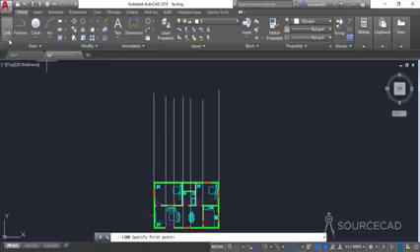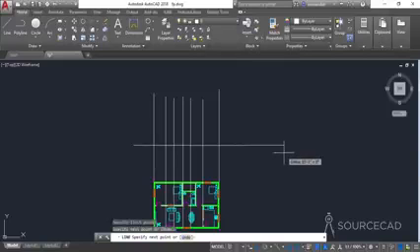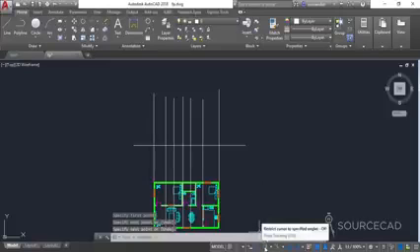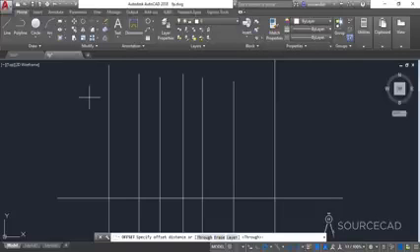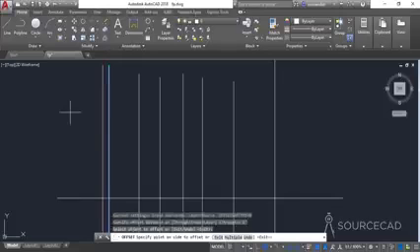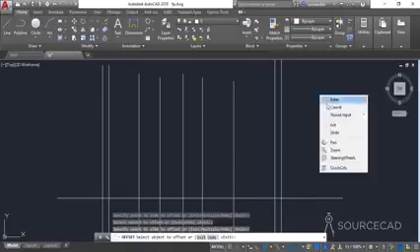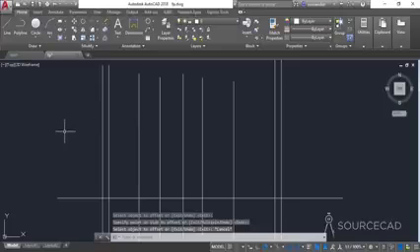Let's make a horizontal line. So I'll go to line tool and I'll roughly choose this point and I'll make a horizontal line of this length. Now you can deactivate the ortho mode and let's activate the polar tracking. Now let's get back to this one. Here I'll go to offset tool and I'll now offset it by a distance of 2 feet. So I'll type 2 feet and press enter. So now I'll click on this line and click here. Also, you can actually click on this line and click on this side. So that will be the overhang which we'll make for our drawing.